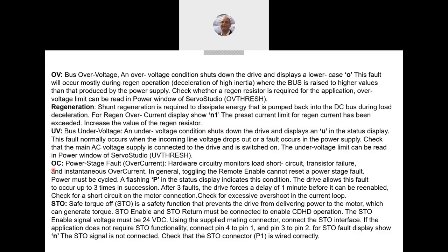We ask you to recycle power on the servo drive and find out what happened and why you have a short between the B plus and B minus. So this is the only fault, I speak for our drive. Let's say all servo drives do the same. They're all running motors and they all have very similar faults. Just the behavior might be a little bit different.